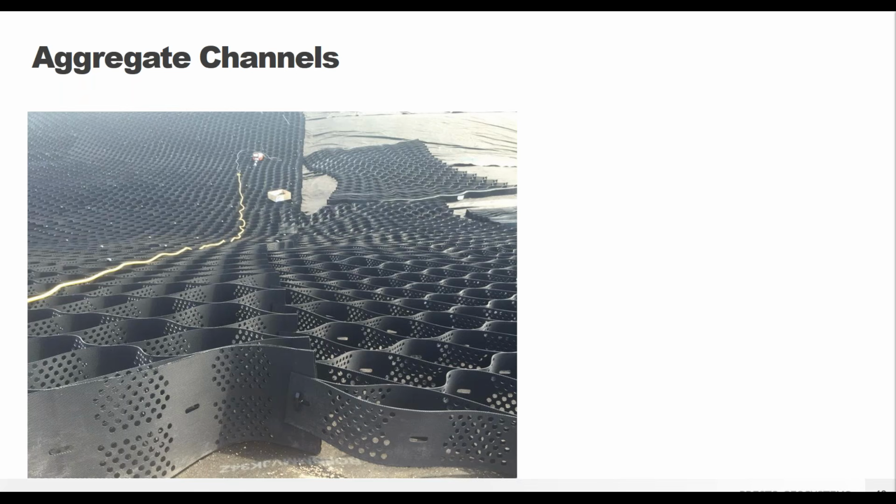And so this is really only possible due to the strength of the ATRA key. And that's the connection device that I mentioned way back in the beginning. If you were to use something like staples or zip ties, neither of those have the strength to be able to withstand a reduction in size like this. And so eventually the panels would have separated over time, creating a potential failure area.